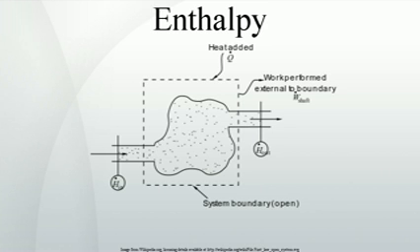Since the enthalpy is an extensive parameter, the enthalpy in F, HF, is equal to the enthalpy in G, Hg, multiplied with the liquid fraction in F, XF, plus the enthalpy in H, HH, multiplied with the gas fraction in F, 1-XF. So, with numbers, 100 equals XF times 28 plus (1-XF) times 230, so XF equals 0.64. This means that the mass fraction of the liquid in the liquid-gas mixture that leaves the throttling valve is 64%.